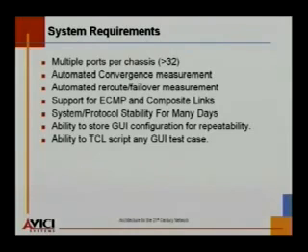We need the ability to store a GUI configuration for repeatability, and we need the ability to write a TCL script for any GUI test case. So a lot of us, when we do our testing, we do it in the GUI first. After perfecting it in the GUI, we want to automate it via TCL. We want to make sure that everything we come up with in the GUI is in fact automatable in TCL.